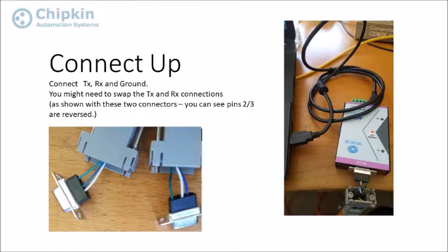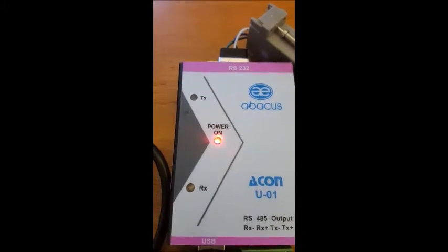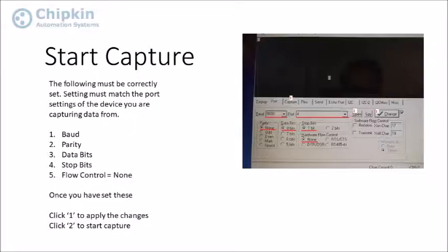If the device is very, very old, 30 years, then you might want to try some low baud rates: 1200, 2400, 4800. Most devices default to 9600-8-N-1 or 19200-8-N-1. It's not that common to see parity. If it is there, it's mostly even, and sometimes you see 7 data bits, 2 stop bits, and odd parity.